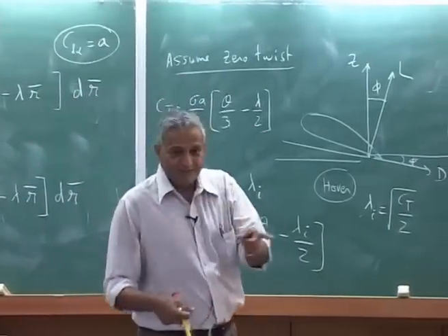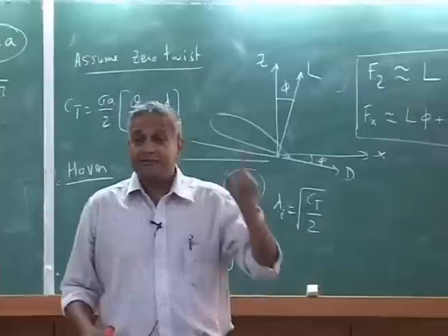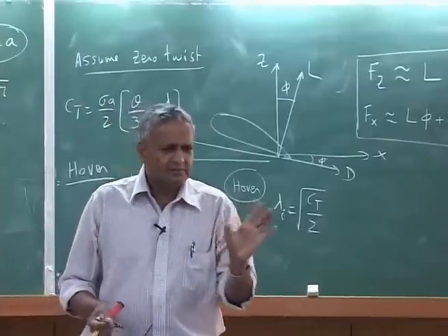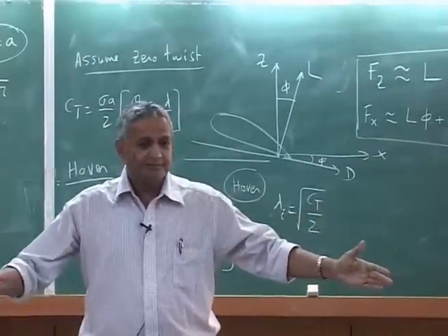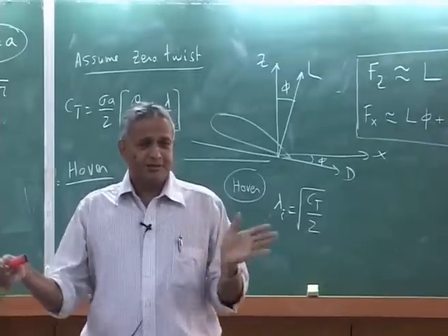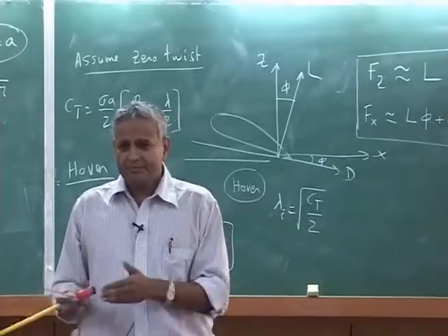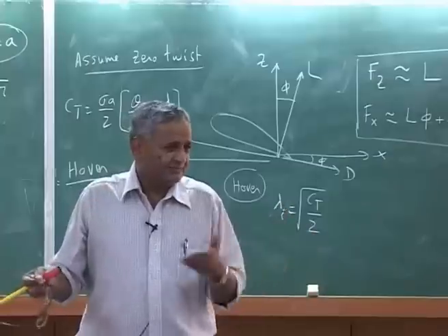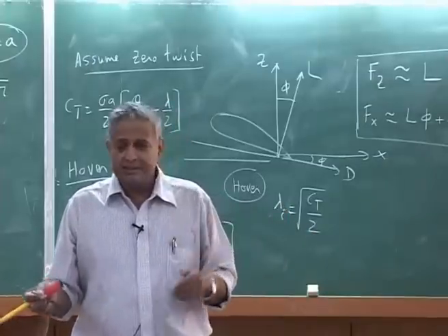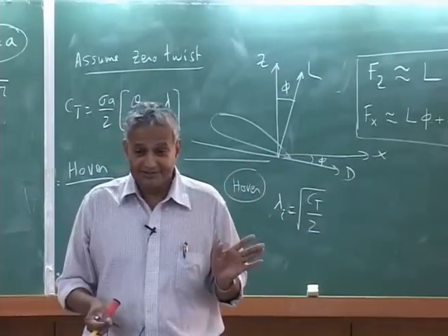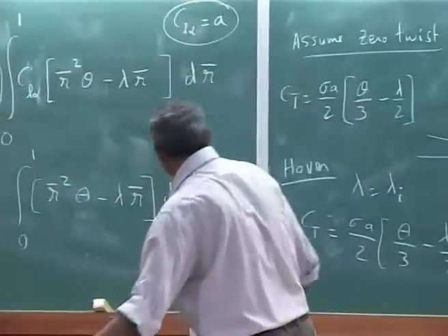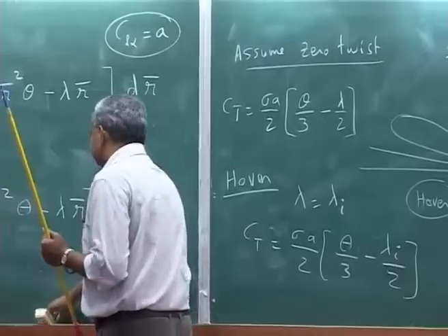Now you see the loop of the calculation in just a very simple problem. If I give you a weight of the helicopter and the rotor radius, some CL alpha, airfoil shape, etc., calculate what the pitch angle should be, you should be able to do it.